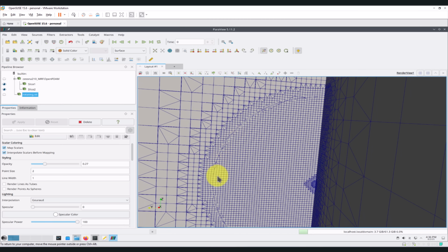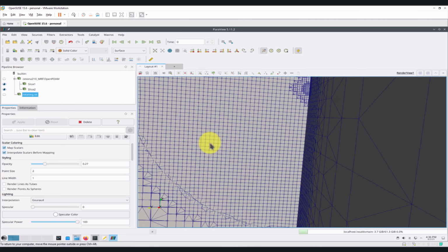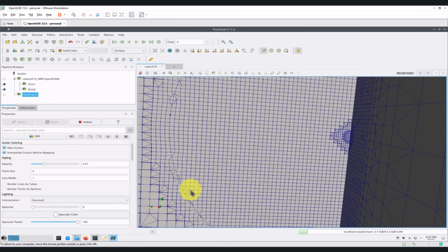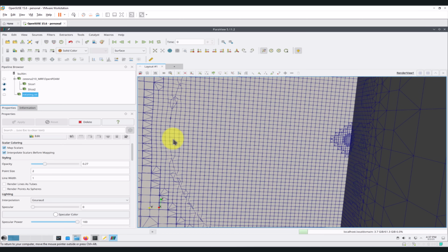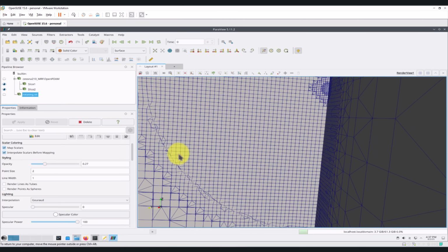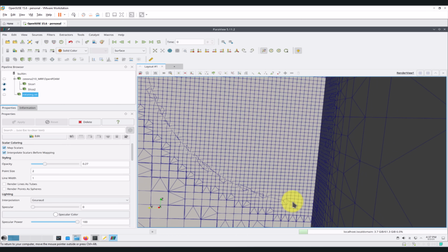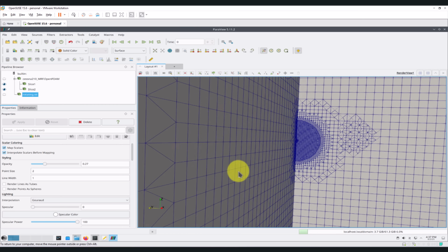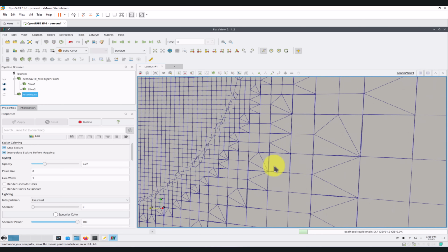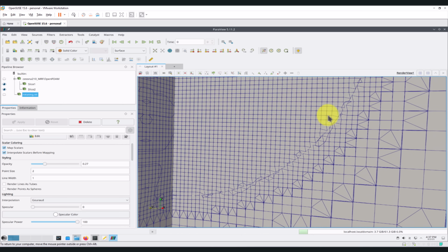So this mismatching can give you problems in the interpolations you are using in sliding grids, but also with the MRF approach, it can add some sources of errors that we're going to see, okay? So this problem usually is solved with the NCC. You improve that. So that's why I say it's better to use NCC, but finer meshes can help a lot.